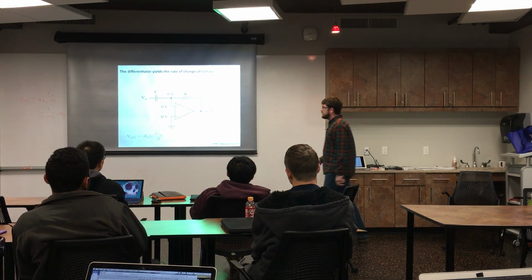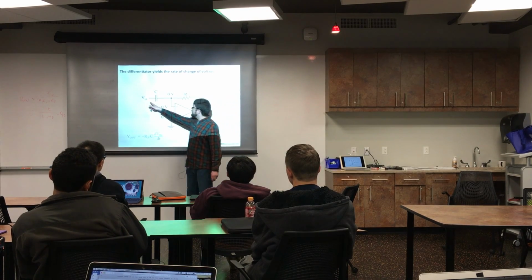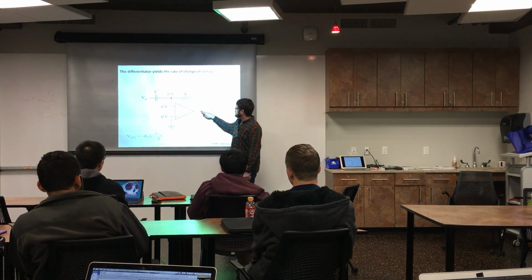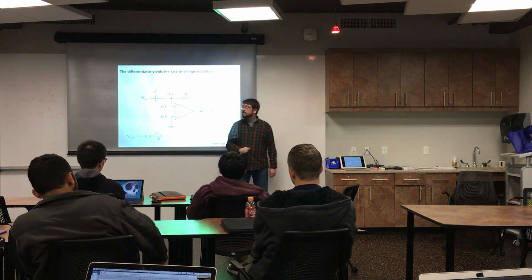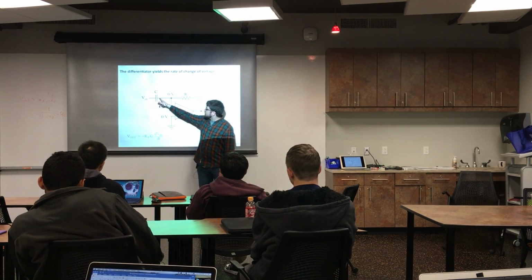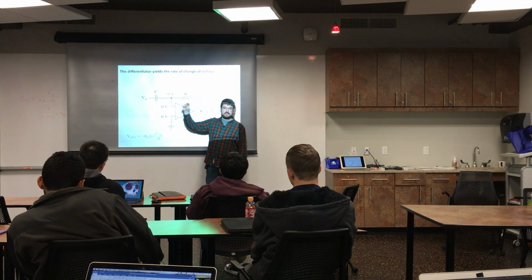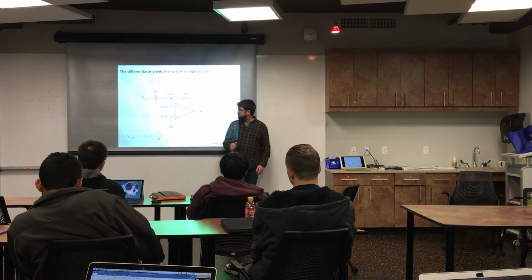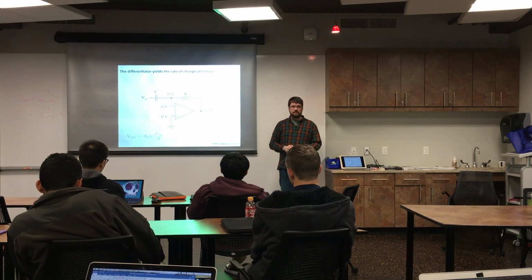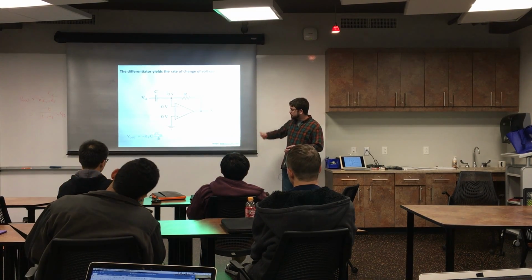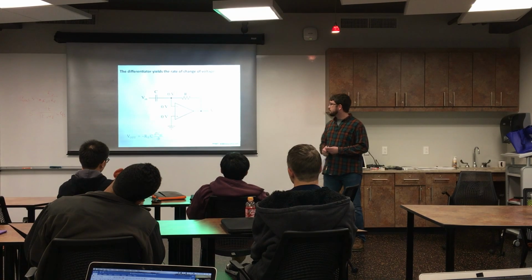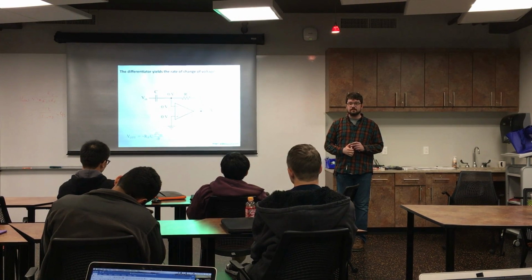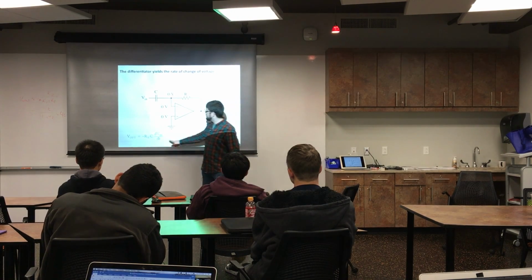So if we make a little circuit like this, where you have Vin coming through a capacitor, you got your virtual ground here, and then a resistor that's going back to the output, the rate of change of the signal gets coupled into the circuit through the capacitor. The DC portion gets blocked out, and the combination of the capacitance and resistance sets the time constant for this circuit. And so you can plug that into the formula down there and figure out what V out you would get given a certain rate of change, dV/dt, here.